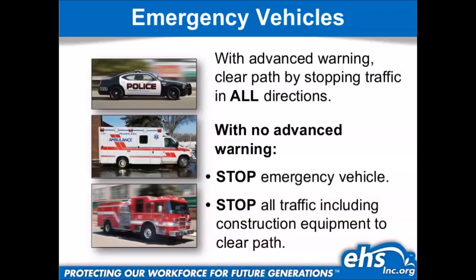If we've stopped traffic on this end, that normally means the other end's flowing. So you're supposed to stop the emergency vehicle, communicate with the other flagger and tell him to stop traffic and move all equipment out of the roadway. Once you've verified with the other flagger that the roadway is clear, then you allow the emergency vehicle to pass. And again, this isn't what we say. This is what the CAMUTCD says. So this is something police officers, EMTs, and the fire department should be aware of as well.